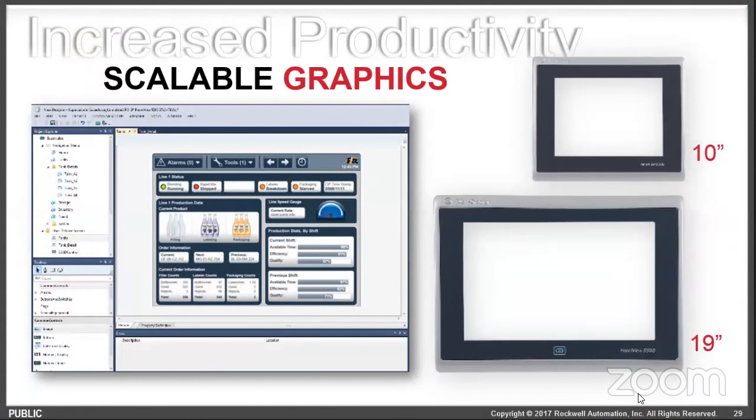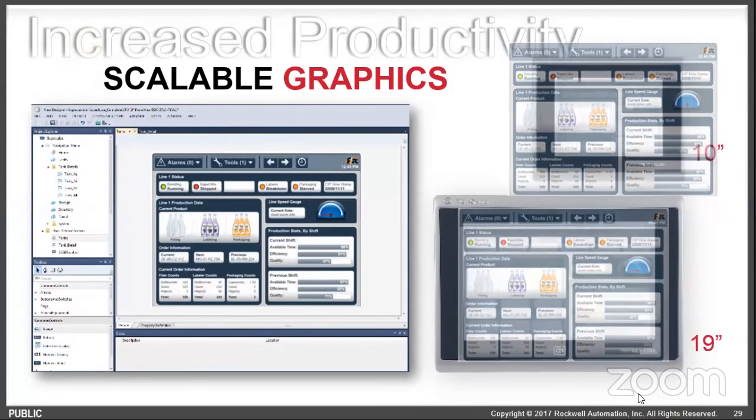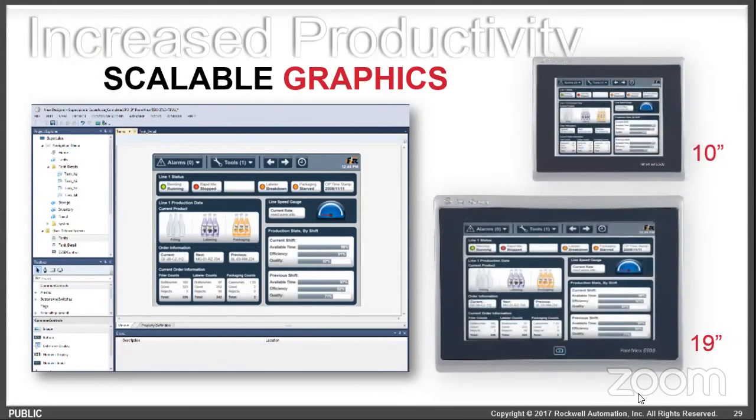Something that's a little bit different as well is how graphics are actually rendered on the panel itself. So you have View Designer there, you're making yourself an application, and because these are scalable vector graphics, you can take that same application and put it on multiple different size screens, and it's going to properly scale. Whereas before, if you took a 10-inch screen and tried to put it on a larger panel, it would stretch, and when you take a bitmap graphic and stretch it, you get a lot of jagged edges around graphics, or the other way around, you look all squished, and nobody wants to have to make the application twice. So do it once, you can move it to different size panels.